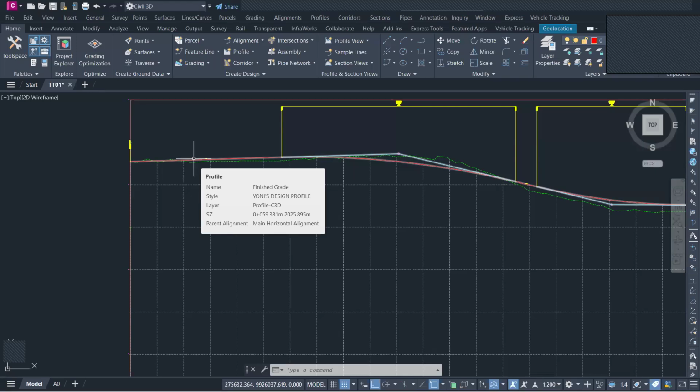So you need to think about that. So we'll do it as it is on site. The contractor, the materials engineer will tell you, we need to excavate 0.6 meters so that we remove the entire of this material. It's purely bad, for example, in arid and semi-arid areas where you have a lot of sand. So we excavate it and dump it away.